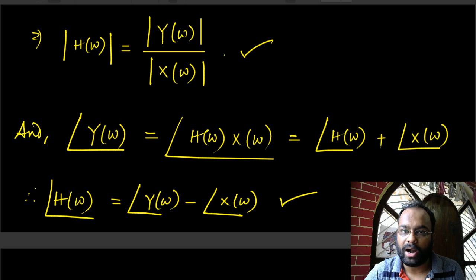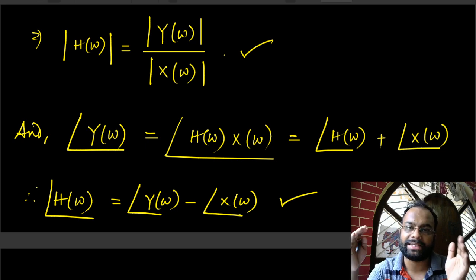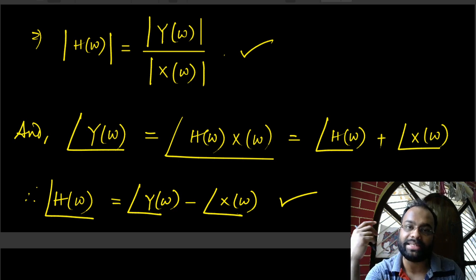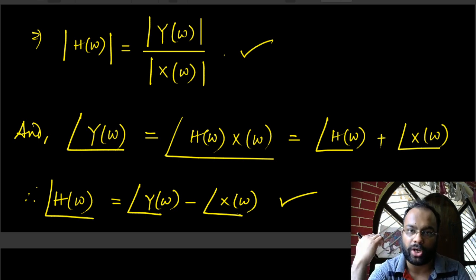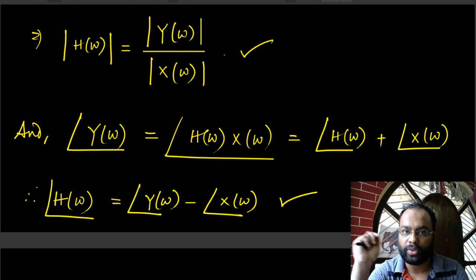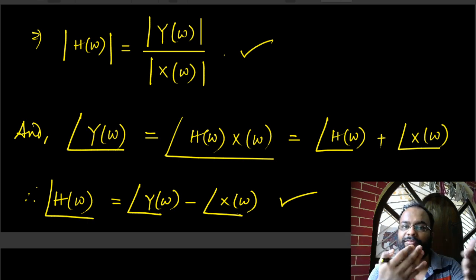And again, I told you earlier that when I excite a linear time invariant system with a sinusoidal input, then in the steady state the output is also a sinusoidal signal, right? The only thing is that the amplitudes and the phase angles will be different. You already know that from circuit theory and so on. We're discussing steady state; we shall later learn what I mean by steady state. For the moment, it means after enough time has elapsed.